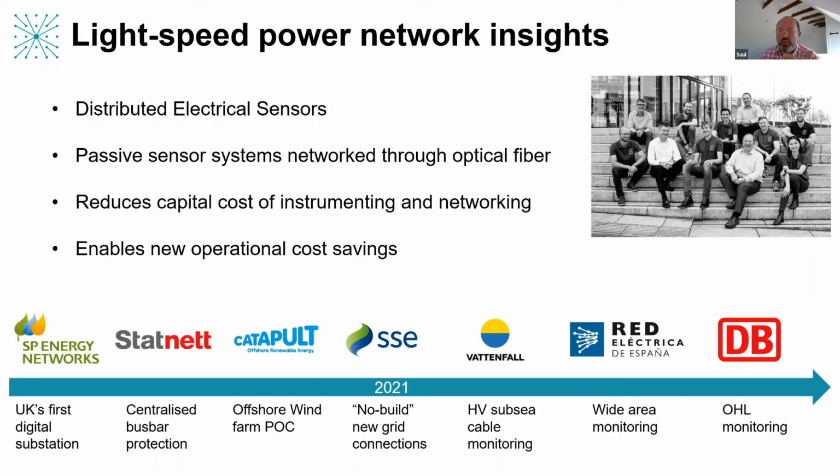At each of those locations, you no longer need civil works and buildings, power supplies, data network, telecommunications, GPS clocks, and all of the equipment that's traditionally associated with powered instrumentation. So this is a smaller footprint with less equipment, a lot greener, certainly more locations and a faster way to get a lot of data brought back centrally to give you better visibility and control of the network. Yes, it reduces the capital cost of instrumentation, and it radically reduces the cost of networking sensors together, which is a major headache for wide area management systems like PMU measurement and state estimation.